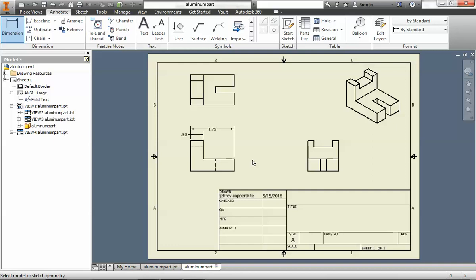And again, you don't have to type those dimensions in; they are configured automatically from the part. So if you get a dimension and it's not what it's supposed to be, that means you need to go back to your part and change it. Okay, you would of course be adding dimensions to this until you have answered the question of is there a way to tell how big everything is in the part, and then you'd be fine.